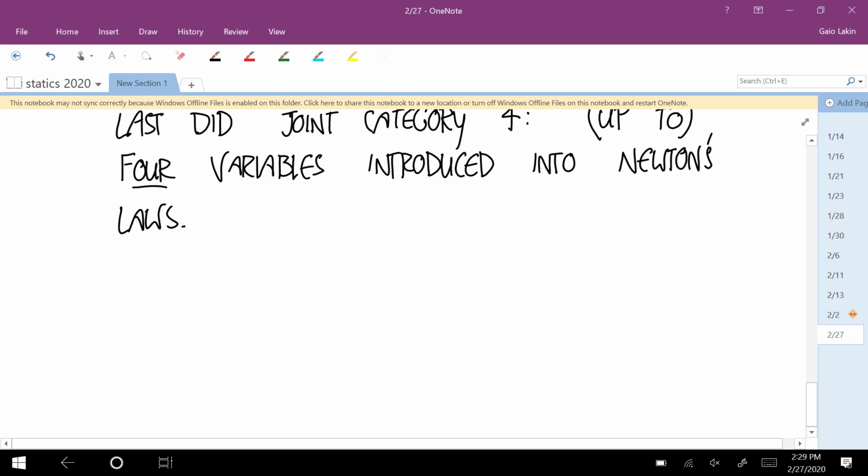So now think of this not as a single pin joint, but think of it as 2 pin joints that share this axis, okay? So if I try to rotate this little stick like this, this pin joint will provide a downward force. This one will provide an upward force. And that's a lot more effective at keeping this rotation from happening than the couple being applied inside the joint itself, okay?